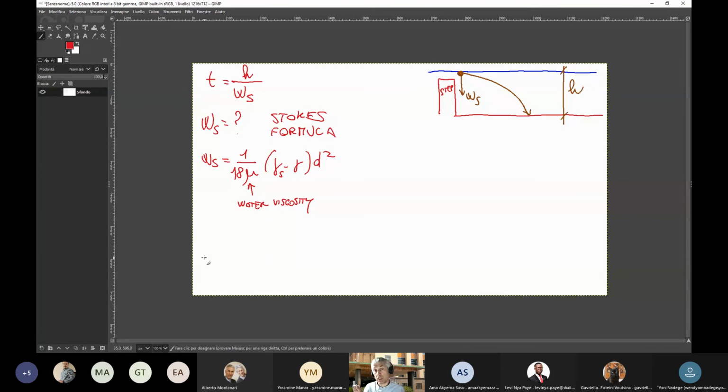How to fix it? Usually you have limitations for the water use downstream. So if you have to use the water for civil water supply, you can allow a maximum diameter of particles in suspension. If you have to use the water for hydropower generation, in the same way, you have a limiting diameter. So the limiting diameter is dictated by the regulations, usually by the water use.